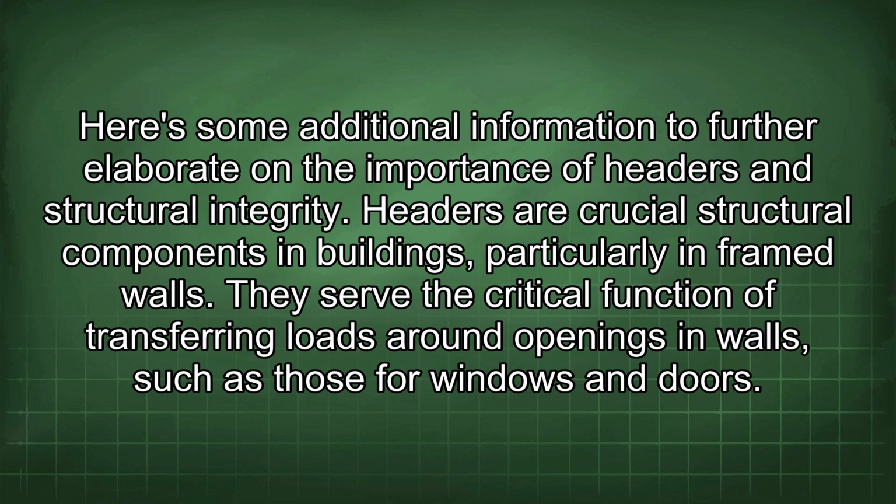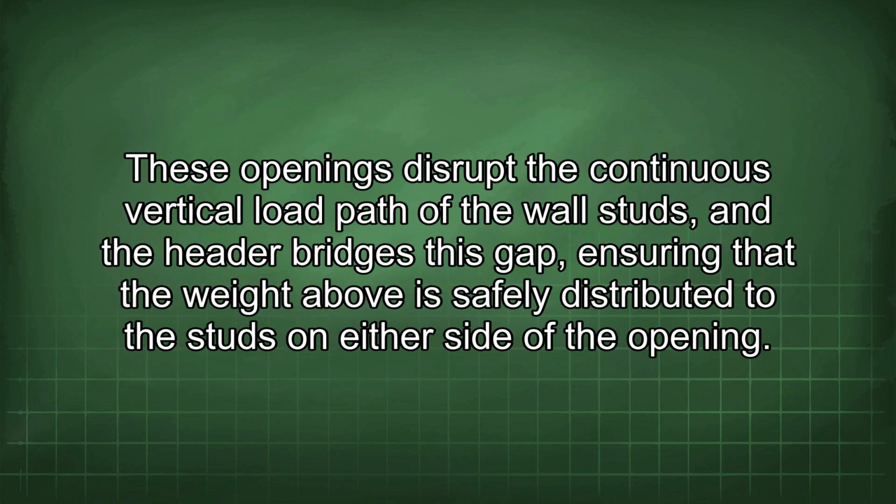Here's some additional information to further elaborate on the importance of headers and structural integrity. Headers are crucial structural components in buildings, particularly in framed walls. They serve the critical function of transferring load around openings in walls, such as those for windows and doors. These openings disrupt the continuous vertical load path of the wall studs, and the header bridges this gap, ensuring that the weight above is safely distributed to the studs on either side of the opening.